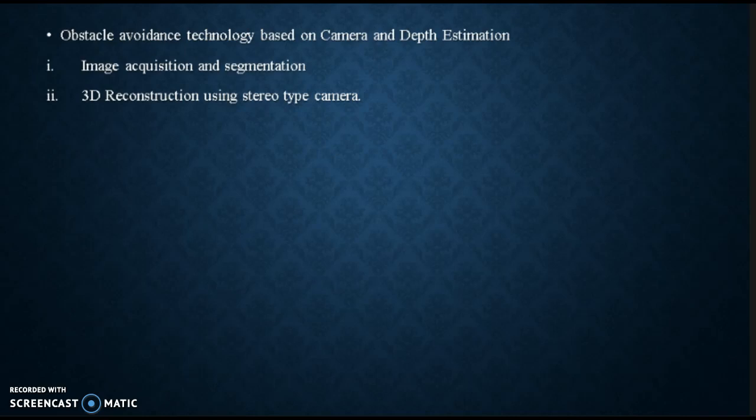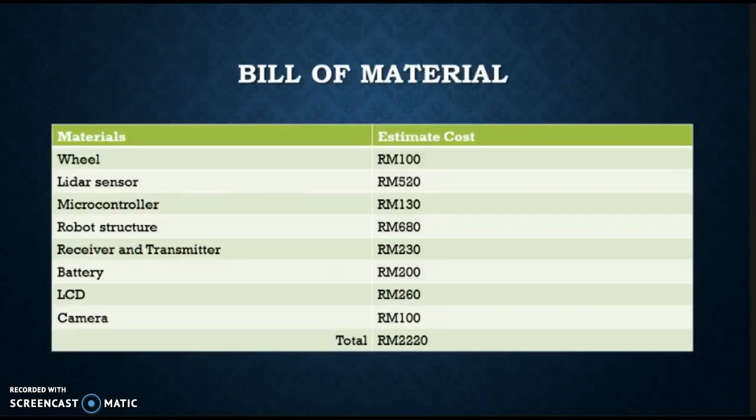Thus, two PID controllers were designed to control linear and angular speed using the linear distance and the heading difference as error functions. The robot state, position, heading, direction, and camera angle is constantly updated by a dedicated thread which reads the encoder and computes the new state for every iteration. In this way, an update routine runs in the background, supplying the whole system with a constantly up-to-date state of the robot.